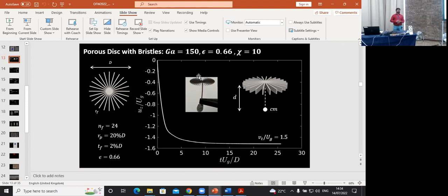Currently in my model, permeability is kept uniform in 3 directions, but since we are inputting permeability as a tensor, we can code it to behave in a different way. But we need more data from experiments on how the permeability changes with the radial variation of the porosity. There are some empirical formulas considered in the literature, but it's not so robust for every application.